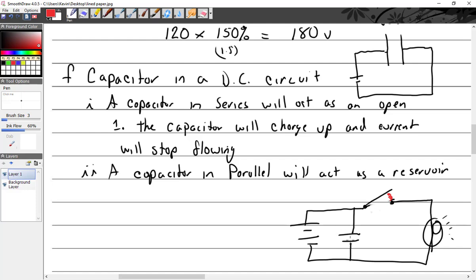So you can put a filter like this in. When the switch is closed, all of the current flows around through the circuit, not through the capacitor. As I start to open the switch, I'll personify the electrons again. Electrons are flowing, and they're like, hey, wait a minute, it's getting hard to go this way because there's now a gap we have to jump across. One tells his friends there's a shortcut with absolutely no resistance over here. So instead of jumping across the switch, they all turn around really quick and run down this way, because they think it's a path back to the battery. And they all start piling up on this plate until the plate gets full.